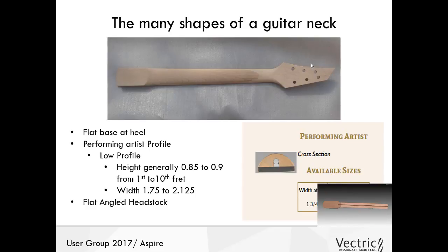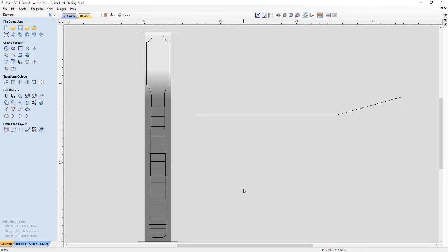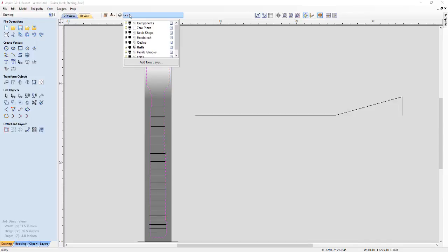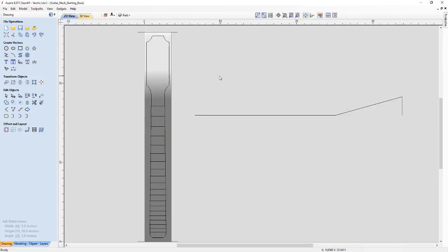So first of all, just go back into the software, and as we're going to be using the 2-rail sweep tool again, we're going to start by creating our rails for our profile vectors to run along. So let's go ahead and select this outline vector, and that should be on the rails layer. Just select it and then press N on the keyboard to go into node editing mode. We literally just want to split this shape into 2 equal halves.